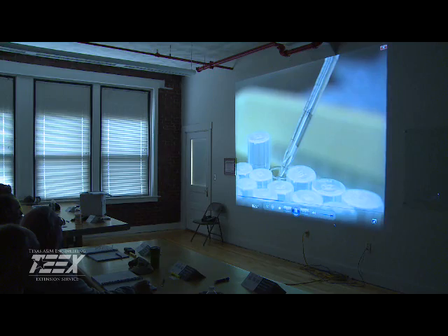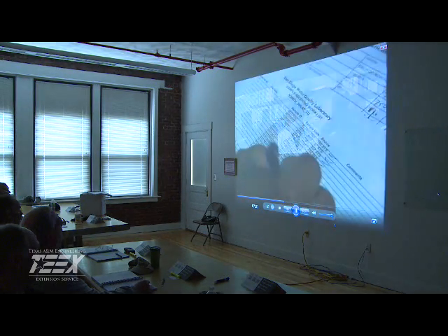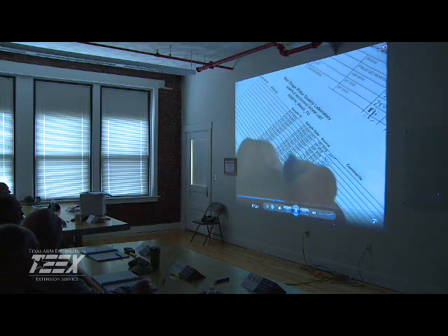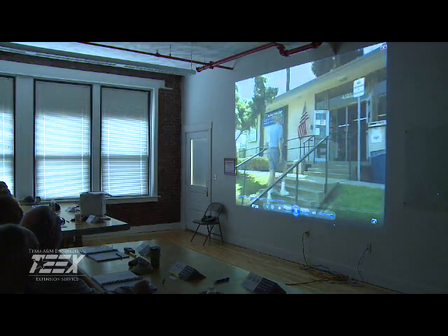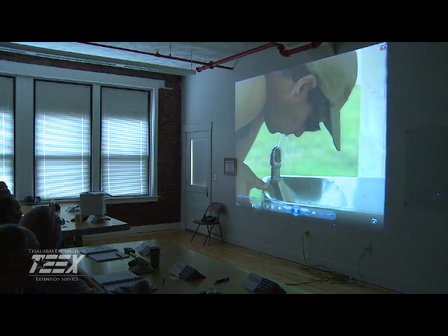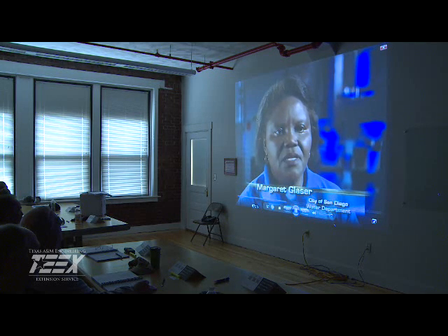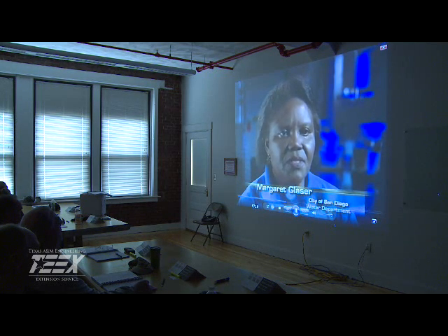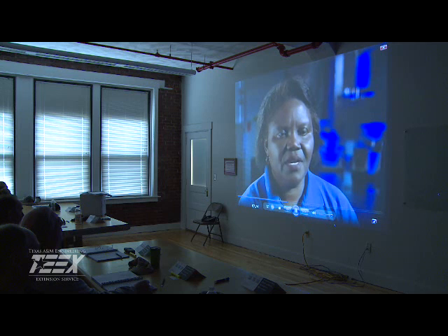on resampling. The sample locations were schools, libraries, and community centers. Water was collected from drinking fountains and bathroom and kitchen faucets. One of the problems with those kinds of sample points is a drinking fountain does not have enough pressure to push the water through so that you get a good sample. So you always end up collecting a sample which has been sitting in the pipes.